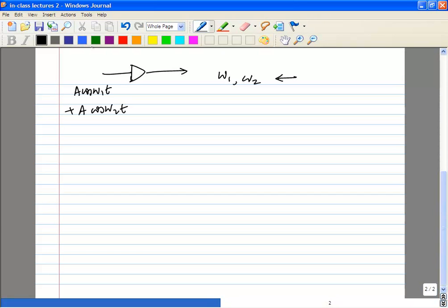And those are the fundamentals, and they'll have a gain of alpha 1 plus, you remember this, and you also get omega 1 plus or minus omega 2, and these are what are called IM2, the second order intermodulation.